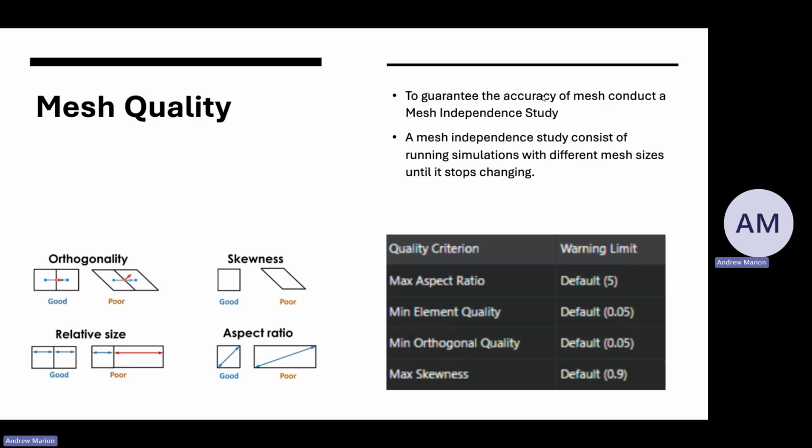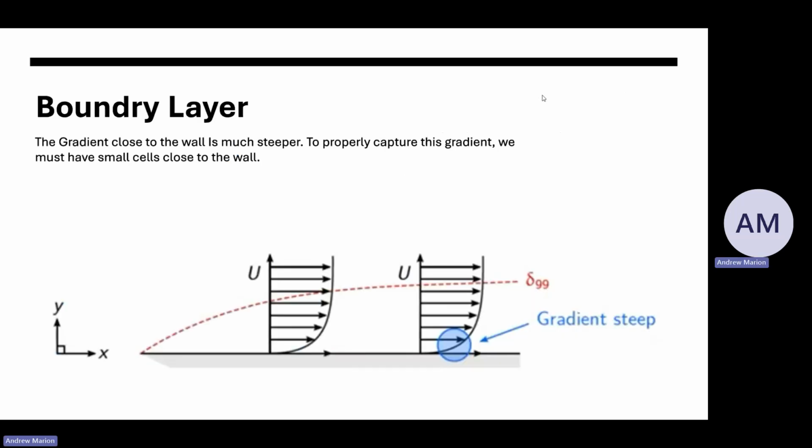But say you need it to be this big, you slowly increase over time. This is exaggerated still, but you slowly increase. Even if you do want to morph and change it so it's not a perfect square, you want to slowly morph and change them across the surfaces or the volumes in this case. Slow changes are always better than sharp ones.